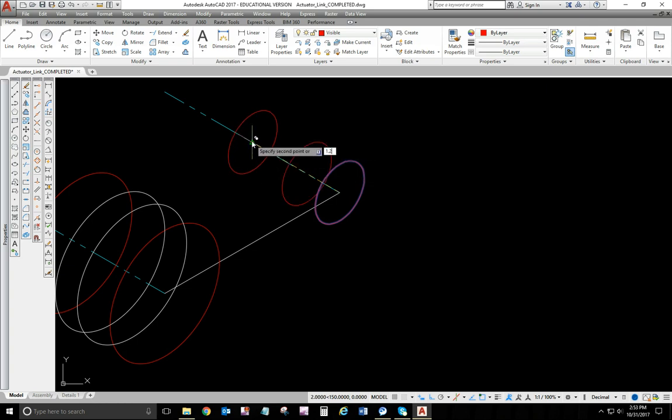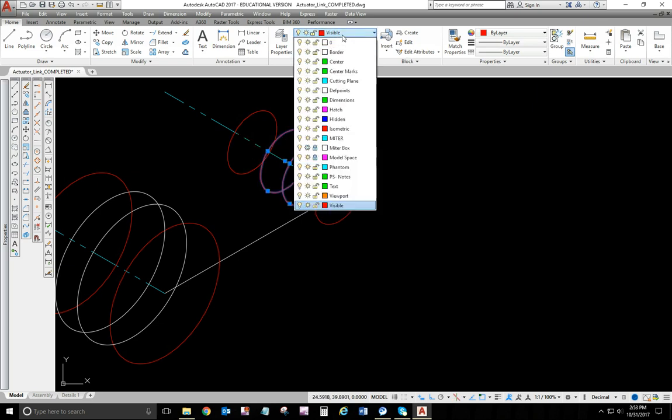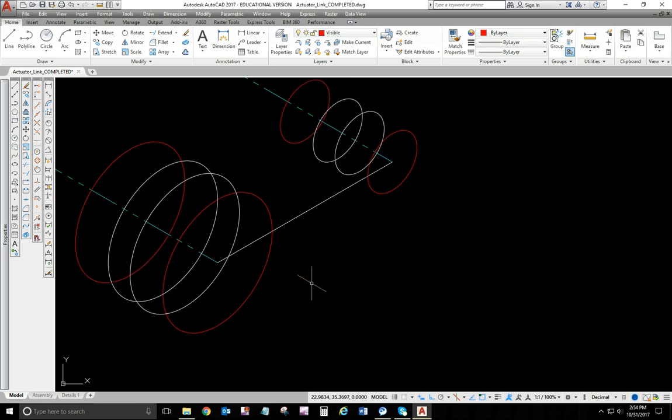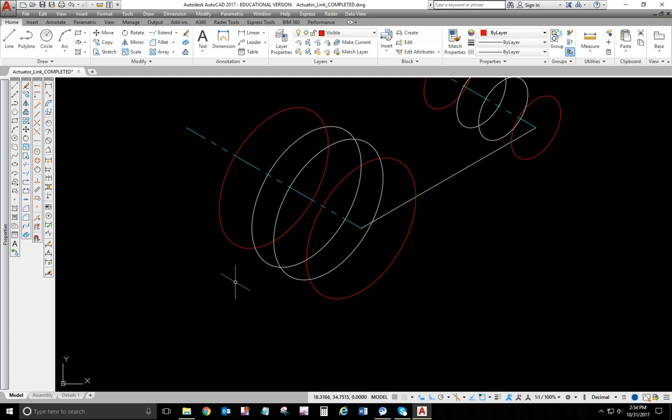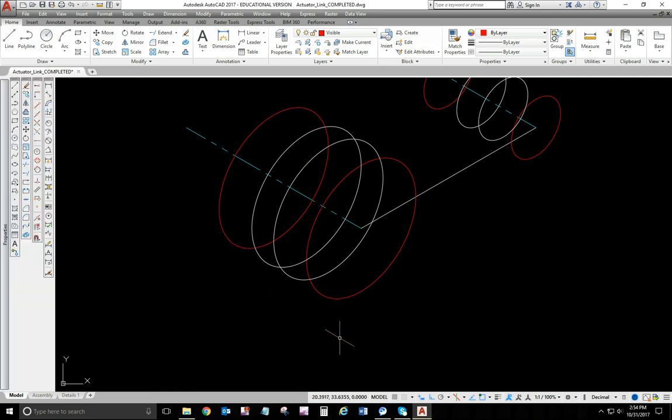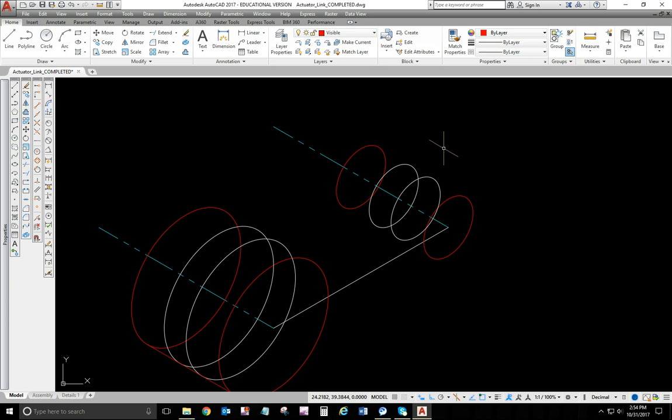.75, 1.25, and 2. Now I'm just putting those on the 0 layer so it's a little easier to see. Now, if you remember, I can't remember when you did ISOs before if we had the tangent lines, but when we got curves and arcs and things in ISO mode, the edge coming across here is just wherever that is tangent, okay? So we'll put a line there, and we're going to do the same up here.